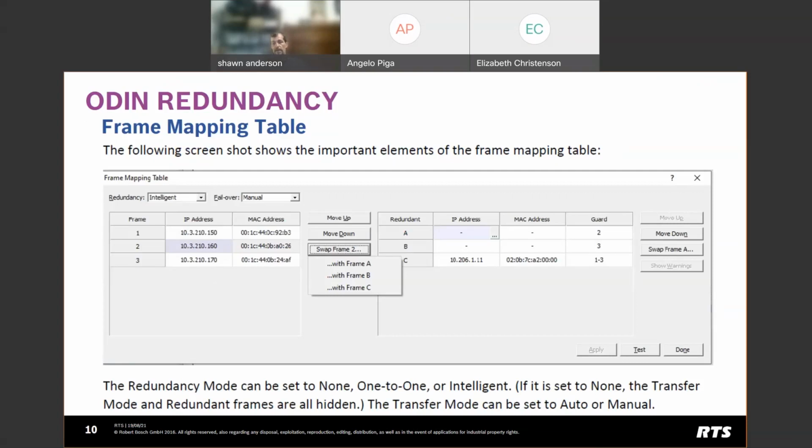I can have it wired in several different fashions. It's plug and play. So I could have the 1 through 8 core frames all linked in sequence to one another, and then guard frame A as the 9th frame, closing the loop. Or I can go core to backup, core to backup. It does not rely on a set of fiber interconnects. It's a plug and play ring. You just need to make sure that all of the units are part of that ring, and it will resolve the connections themselves.